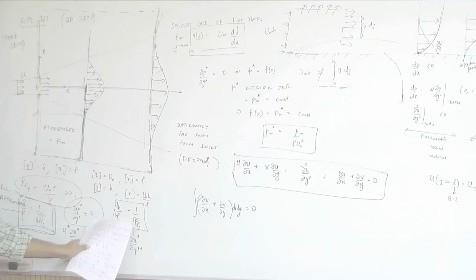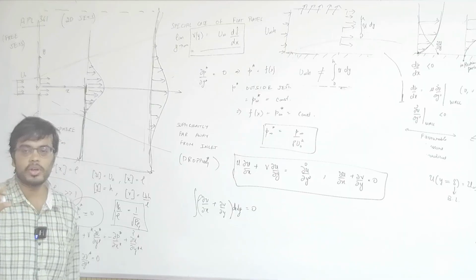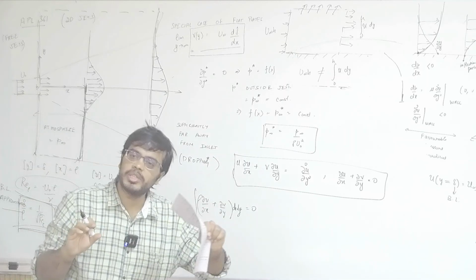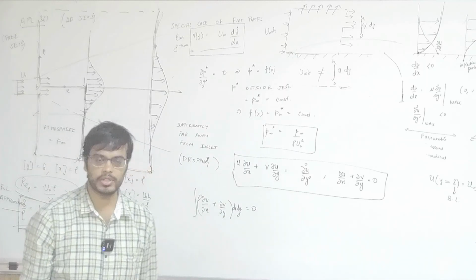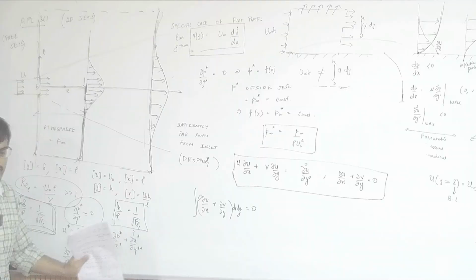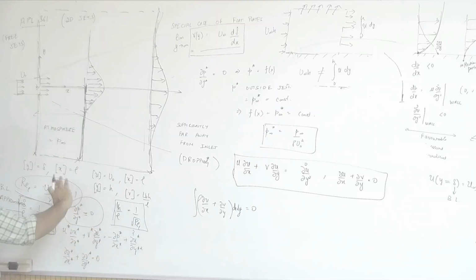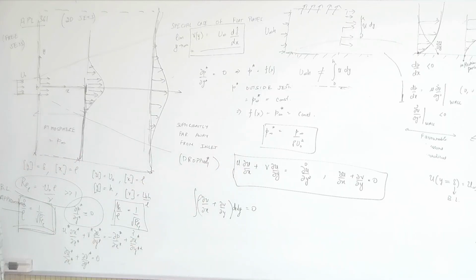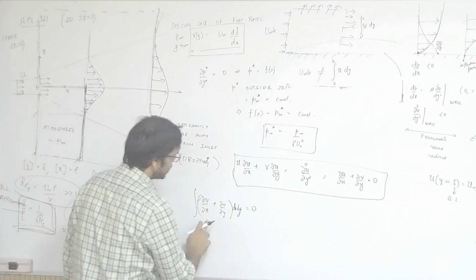So this should also tell you that the boundary layer approximation in free jets basically means that your Reynolds number is high enough and h by L is small enough. Which means if your diameter or the height of this orifice is some 1 centimeter, then you are much greater than 1 centimeter away from the orifice. That is what this approximation results in. So all of the analysis that we are going to do is sufficiently far away from the orifice.